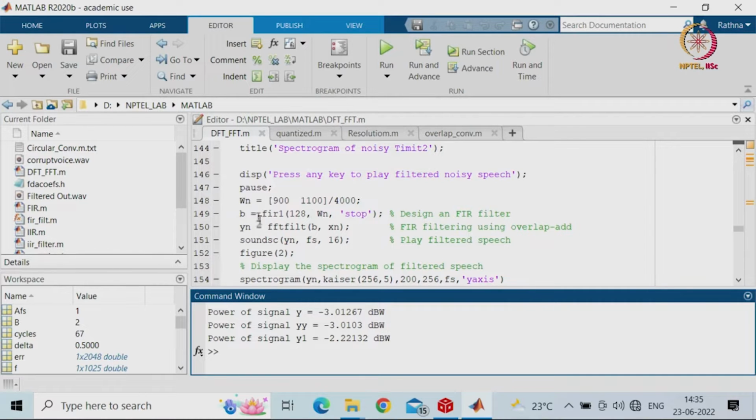Now, you can define the window. Because the sine wave we have created is 1000 hertz, that is 1 kilohertz, I want to eliminate that. So, your filter has to be a band stop filter or a notch filter, which you can design using the filter design toolbox, or you can use the command window also. So, the stop band region is 1000.